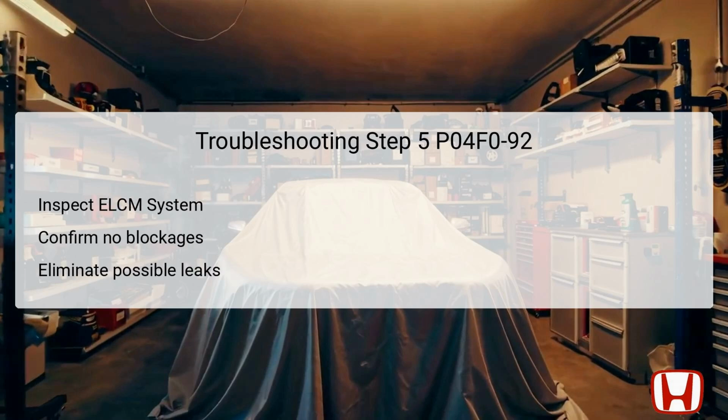The next step is to inspect the Evaporative Leak Check Module, ELCM, system. This involves checking all connections for any signs of blockage and ensuring there are no leaks or damage present within the ELCM components. This system is crucial as it monitors the integrity of the EVAP system by detecting leaks that could affect vehicle emissions. If faults exist, they must be addressed immediately to secure the proper operation of the entire EVAP system. By confirming the condition of the ELCM, you will have a clearer understanding of whether it is contributing to the issues identified by the DTC.